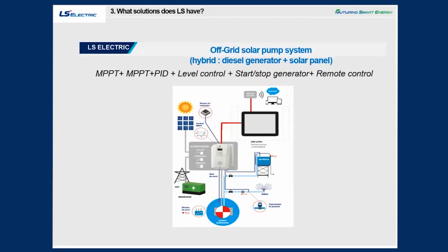0.5 Hertz continuously several times at 40 Hertz, which is the minimum frequency for pumping. From the customer's point of view, since the generator does not need to increase the frequency above 40.5 Hertz, it is possible to purchase a generator with a small capacity, and this function will be a competitive factor as there is no need to purchase a separate controller.